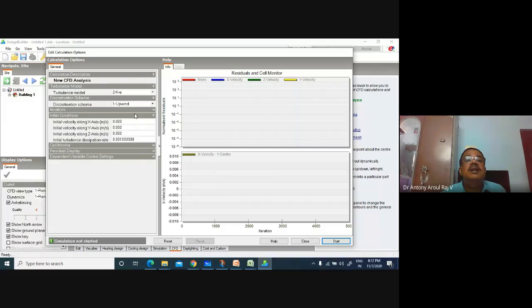Initial condition usually does not apply in CFD, we are not doing a transient analysis. It is steady state analysis only. Then why do we have an initial condition? It is actually an iterative solution. When you go for an iterative solution, you give the initial values. Yesterday we saw the Gauss-Seidel procedure. In the Gauss-Seidel procedure, for solving the problem, we go with the first set of guess values. Gauss-Seidel is actually a guess and correct procedure. First, we have guess values, so those values we are giving throughout the domain.